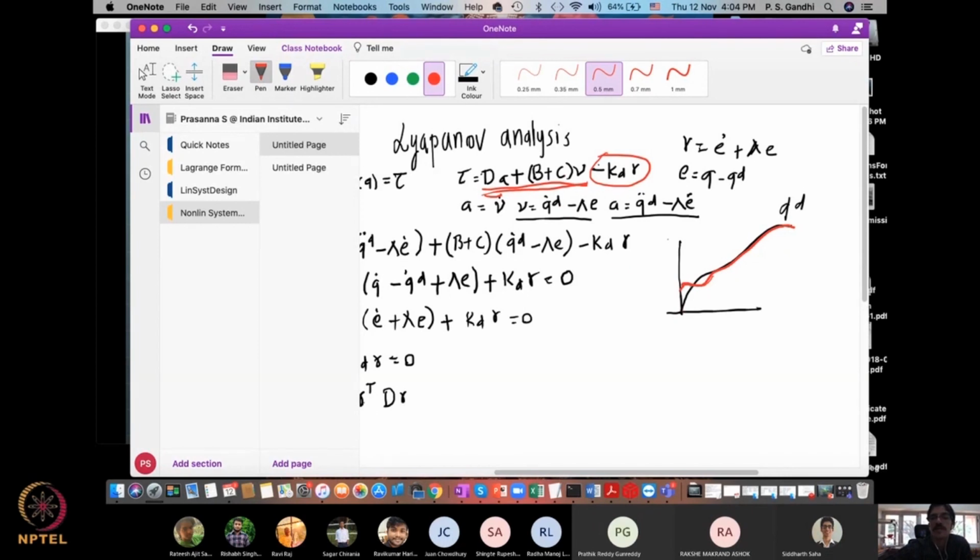And say these transients are initially driven. So initially, with the transients, this term is going to be contributing more to the control action. Okay, and once the transients die down, this term also will go down. So you can afford to use very high gain for this Kd part here.